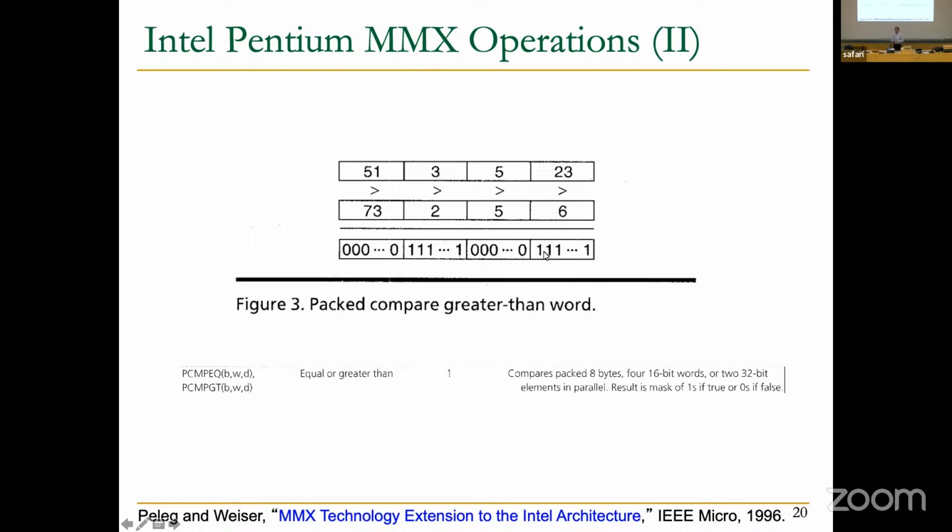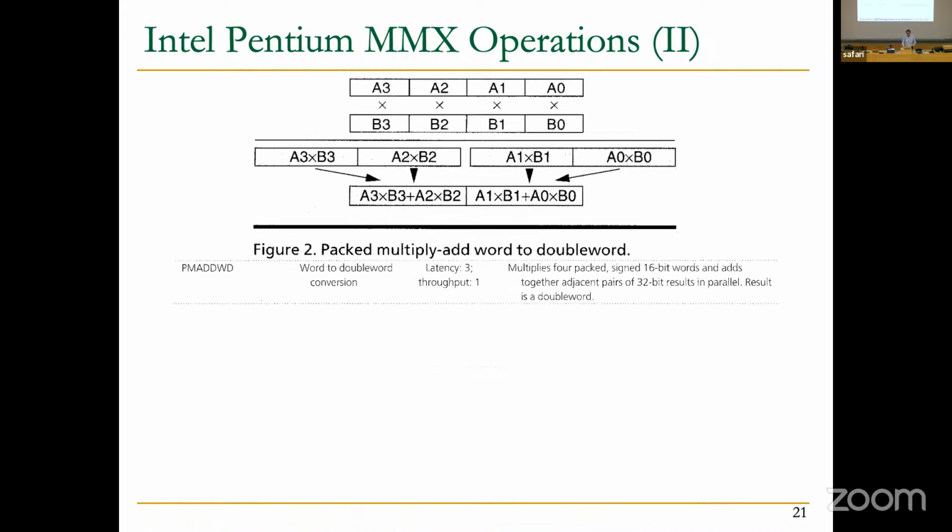So now what you're seeing here is you're creating a mask. Remember the vector mask register? We had that as a special register in a SIMD processor. Well, we have it in a general purpose register over here. The destination register specifies the mask. And we're going to use that as a data element to decide which operations take effect or not by programming this in a nice way. Does that sound good?